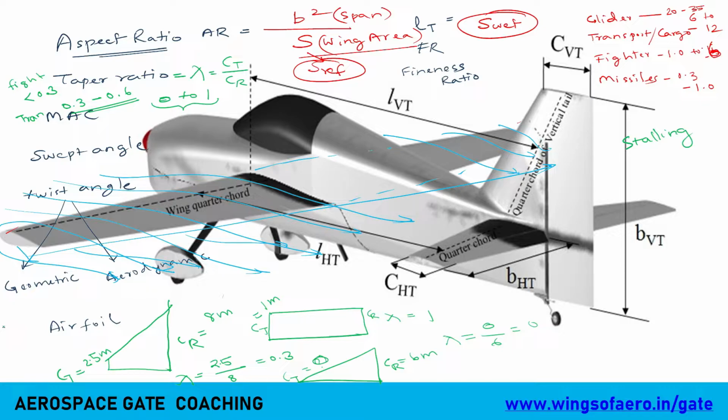Maximum angle that can be attained by the aeroplane. Maximum angle of attack. So that means if this wing has one kind of control surface, and it goes up to 90 degrees, is that the maximum angle you are talking about? Ma'am, critical angle is the angle where the CL generated is highest. That's the point. So when you talk about the critical angle, you should define what is meant by critical.